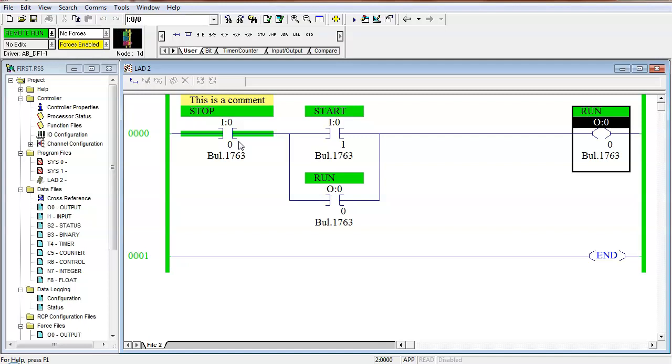And that one thing right there gets people that have had motor controls. They've had motor controls, it screws them up. Because in motor controls, we use a normally closed push button, and that's the symbol we use for a normally closed contact. Okay. So remember that. So I will correct you on it. And OSHA even says that you should always use an examine if closed instruction, right, for a stop button.